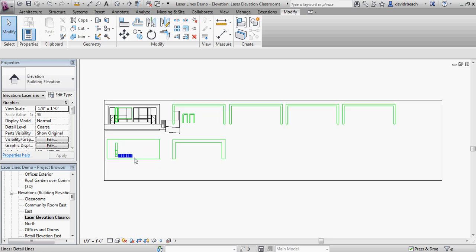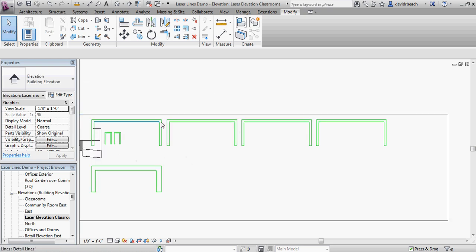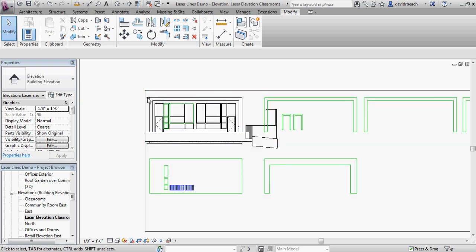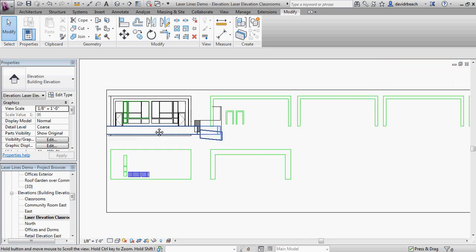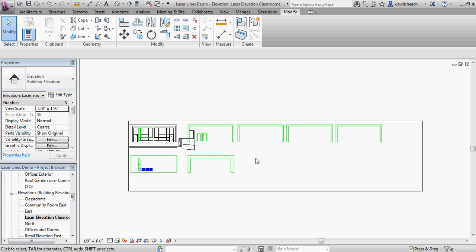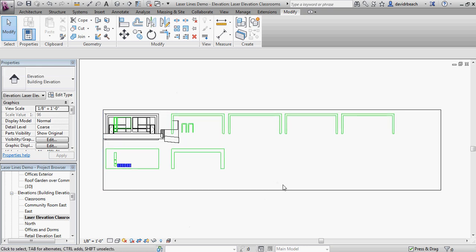Again, what the laser gives us an opportunity to do, to me, it's not about just quickly cutting out two-dimensional shapes, but it gives us the opportunity to think about more repetitive elements where I can begin to build up a building facade that has more depth designed into the facade, simply by the fact that it doesn't take me any longer to make these 4 pieces and to give this some really nice 3-dimensional depth and to stack up 2 or 3 sets of mullions. All I have to do is copy those lines over, and what I get immediately out of that is the idea of a lot of depth in the building facade with incredible accuracy, because the laser is going to cut in a very precise kind of way. So think about using the laser in that kind of way. Revit works great. Use the elevation as a background template and stick with detail lines.